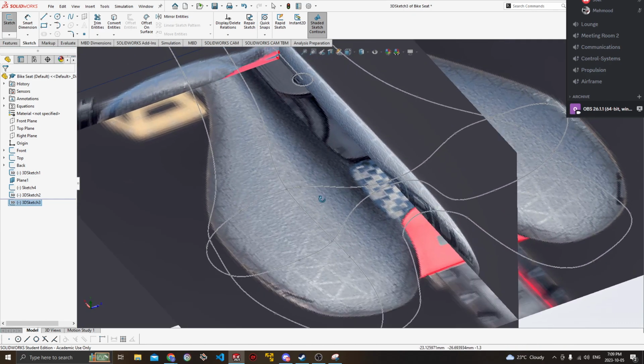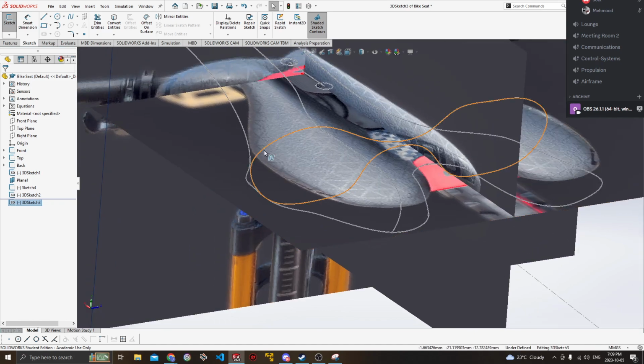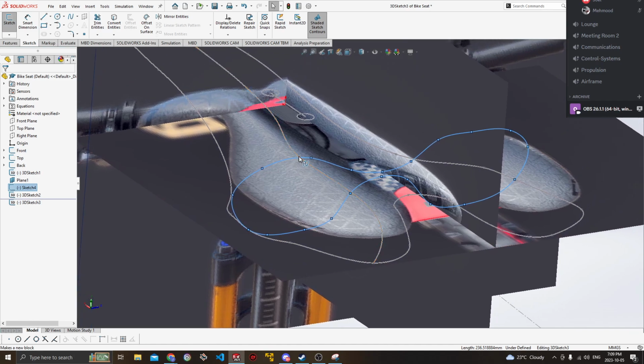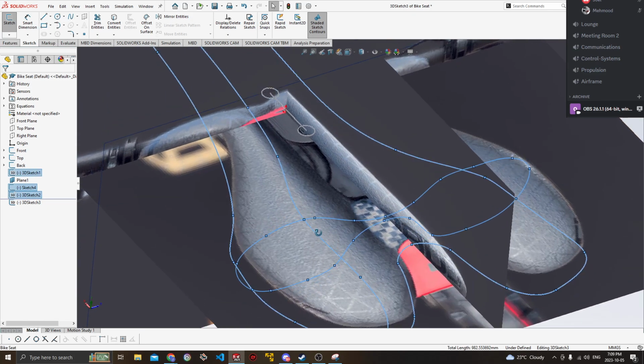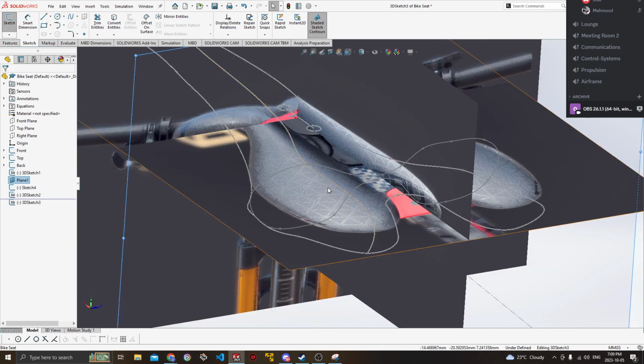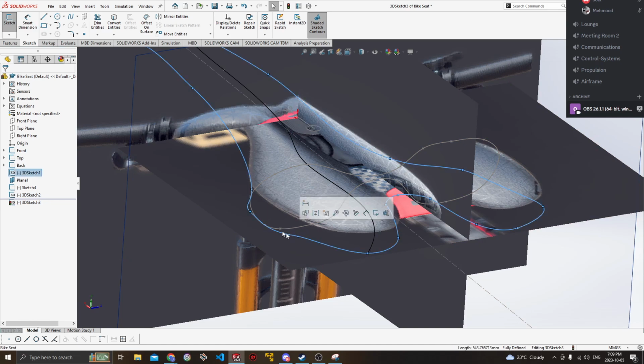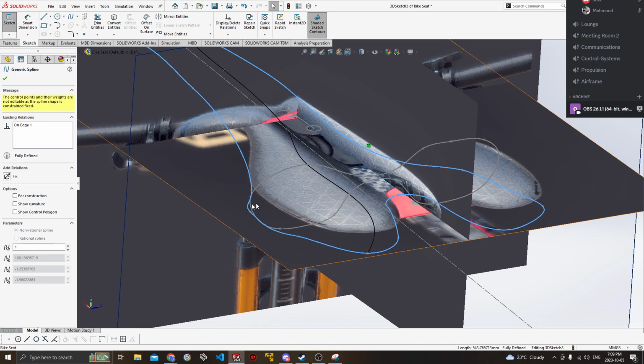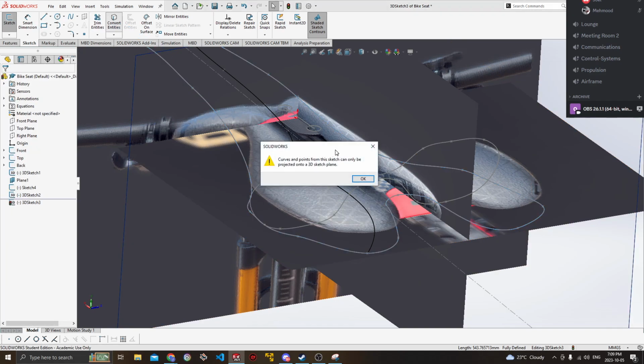So for example here, we can see that there's a few closed loops, right? This spline here intersects with this one, and then this one, and that region within those three splines between here, here, and here is where we're going to create our first surface. And so what we need to do is just recreate that section, okay? So I'm just going to grab this, and we're going to convert that. Grab this, convert that. Oops. Grab this. And we're going to convert that.